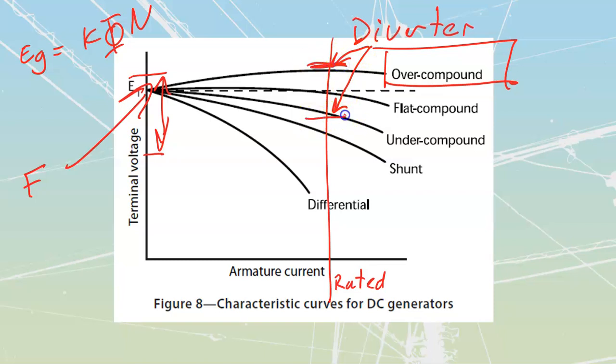So my diverter is really going to allow me to make the variation between these two points, which allows me to do a lot of really funky stuff using these two rheostats, because I can bring this point up really, really high over here and bring this point down really, really low. So I can run this thing closer to a differential, or I can adjust them the opposite way using the same generator, and have this one low and this one relatively high, and go to a relatively hot over compound off of these ones.